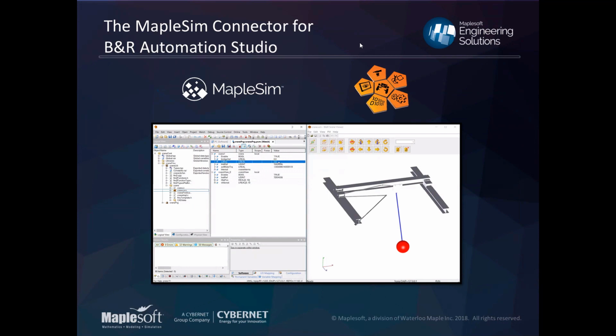And historically, what some folks have been doing to use virtual models to test some of their control strategies is using this technology that's called functional mock-up units. This is a way to take the dynamic model from a software like MapleSim and wrap it up in what's called an FMU and bring it into one of these control automation softwares. With this new connector, however, we've taken it further than that.